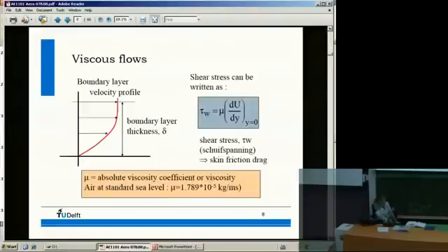So now a plot of what happens inside this boundary layer. Suppose here we have our outer flow. Here we have our object, so the surface of our airfoil or flat plate. And this is then the speed. So the speed decreases from the outer area speed to 0, like this. And the boundary layer thickness is the thickness of the area in which this happens. Quite often it's hard to say exactly, but we report that 99% of the outer flow is recovered inside the boundary layer. And we denote the boundary layer thickness with delta.